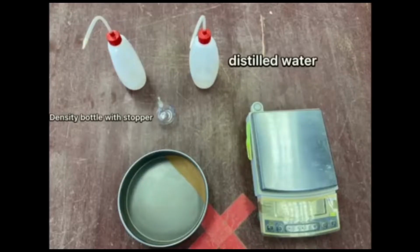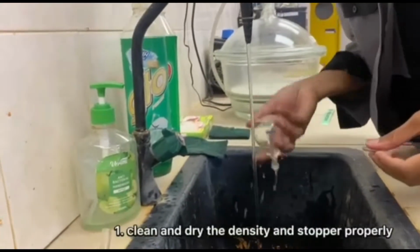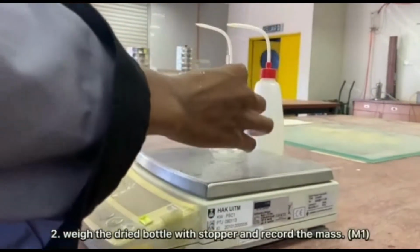The apparatus for the experiment is distilled water, a density bottle with stopper, soil sample, balance, vacuum set, and the last one is a thermometer. First, we need to clean and dry the density bottle with stopper properly. And then weigh the empty bottle with stopper and record the mass, which is M1.